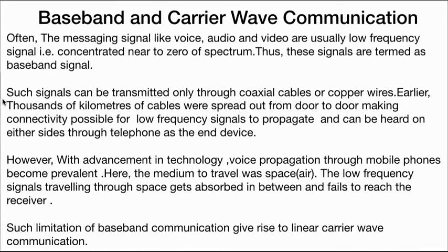However, with advancement in technology, voice propagation through mobile phones became prevalent. Here the medium to travel was space, air. The low frequency signal traveling through space gets absorbed in between and fails to reach the receiver. Such limitation of baseband communication gives rise to linear carrier wave communication.